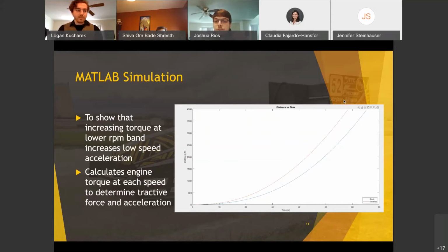The equations for the lines of best fit found above were put into the MATLAB program within a while loop. The while loop keeps track of engine RPM and calculates the torque at each given RPM. The RPM values start at 4,686 RPM and end at 12,686 RPM. This is because the dynamometer data we have corresponds to these engine speeds as its lowest and highest speeds.